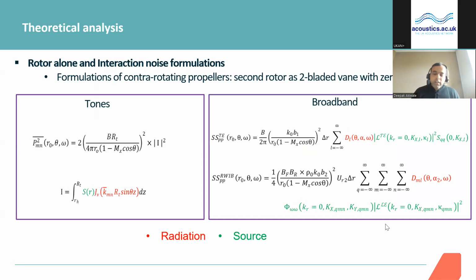So again, similar to the tones and broadbands I explained in the previous slide, I have tried to show similarities between these two formulations. Again, these two formulations have source strength as well as the associated radiation terms. The entire tonal formulation can be collapsed into this generalized formulation, where I is an integral which has a source term as well as the radiation term,